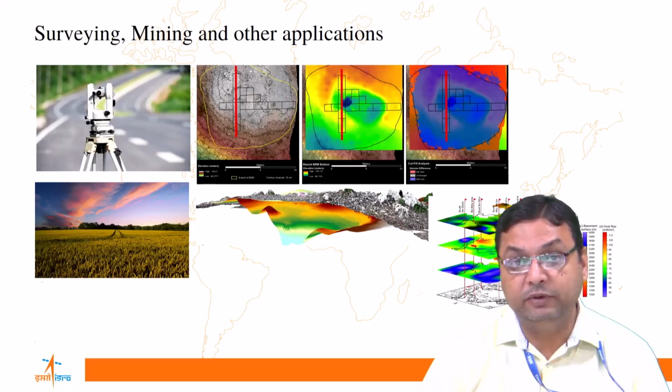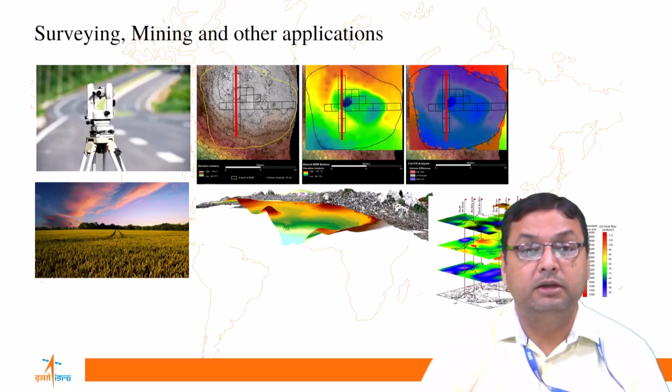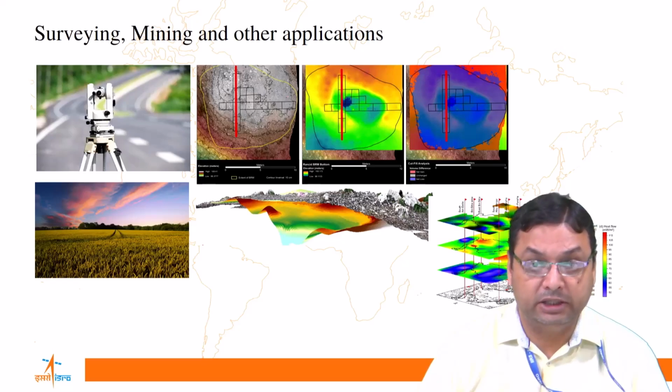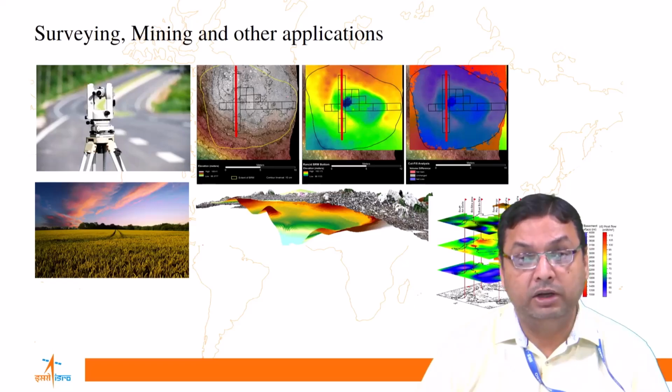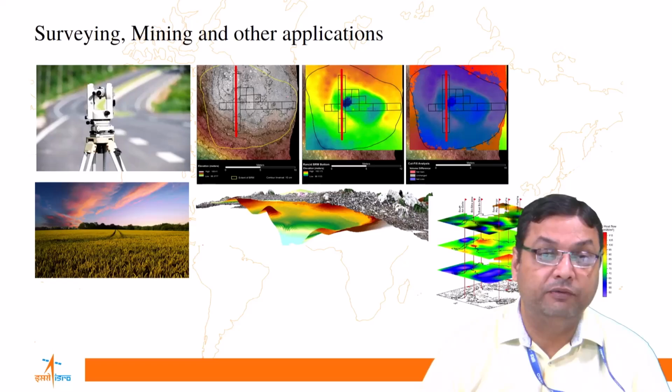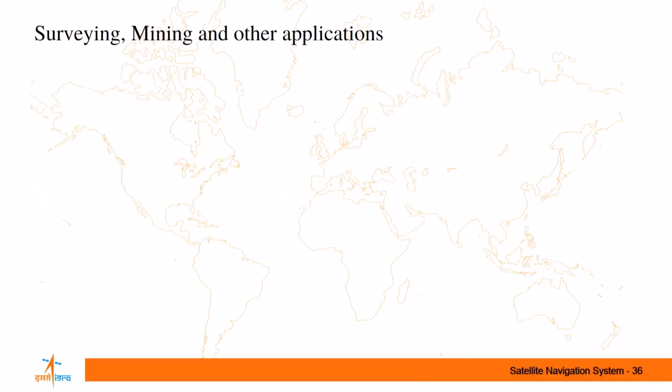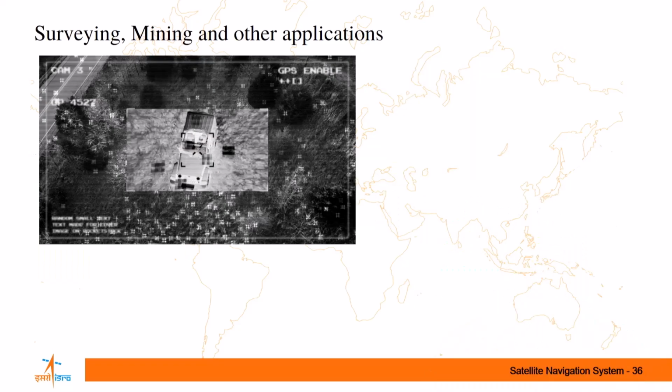So GNSS is a very critical equipment which brings all the datasets which are coming from different agencies to one standard georeferencing system, so that the pixel by pixel matching can be done in different layers, which are basically inputs coming from different departments. So the georeferencing should be with respect to one map projection system, one datum. Then only our models will become perfect. That will attain us more accurate results.